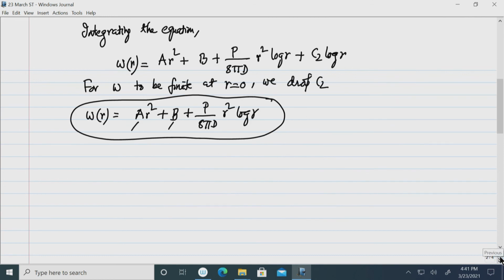So, obtaining this, we now go to finding the constants of integration. That means, the equation can be rearranged in this form, final form, and then we apply the boundary condition. So, boundary conditions are at say a radius a, r is equal to a, at the boundary, the deflection is 0 because it is simply supported, as well as m r equal to 0. There is the radial moment equal to 0.